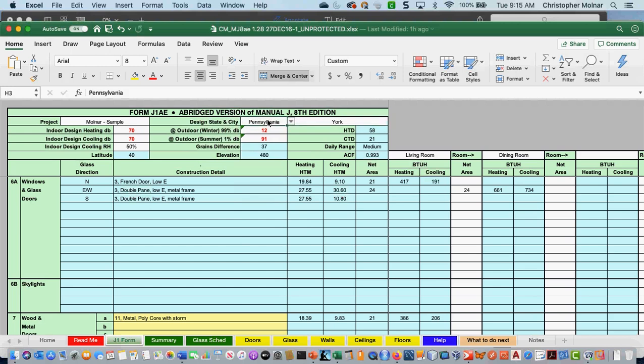I just didn't understand what the information meant, because this automatically fills. It's basically what our outdoor design temperature is. It's our average. Okay, so then what do we expect the winter delta T to be? Because there's other spots on charts for that. Right here. It's the heating temperature difference. The 58 on my sheet that I'm showing you.